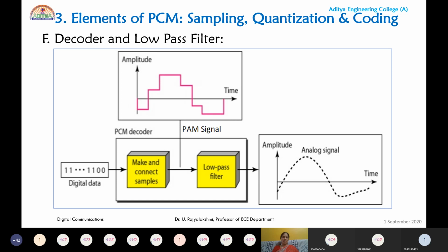The decoder working principle is exactly opposite to the encoder. The encoder converts the discrete voltage value into a binary sequence. The decoder first divides the whole sequence into a certain number of frames that depends on n, each frame consisting of n bits, and then the particular n-bit sequence is converted into analog voltage.